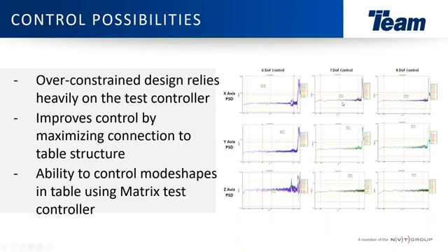You can see once you add that 7th degree of freedom control into the control parameters, you basically clean up the z-axis all the way out to 2 kilohertz, and you reduce some of the lower frequency, 1500 hertz, 1000 hertz content down within the control, within your limits. But you still have this sharp point just before 2 kilohertz on your bandwidth. So then we add the second mode shape.